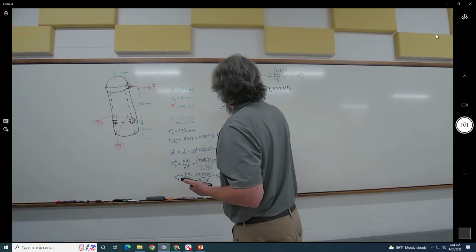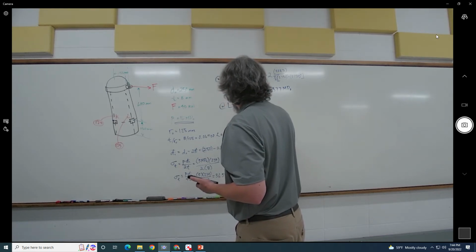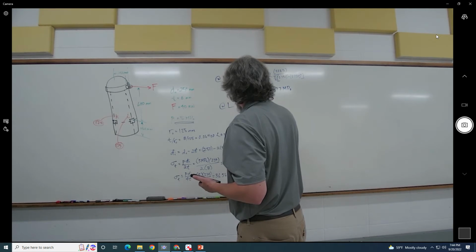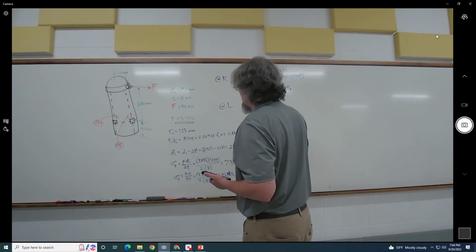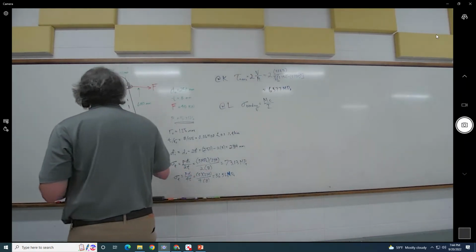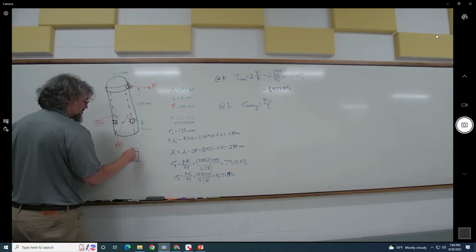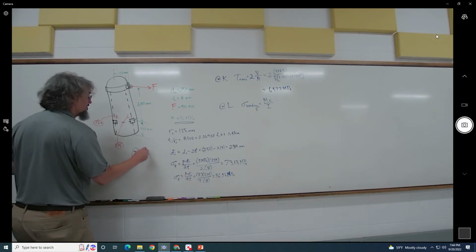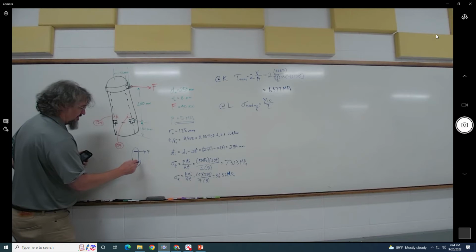And then at L, we could have bending. It's going to be compression, so MC over I. We could kind of do this in our heads, but we could do a little mini FBD, where we have shear coming this way, moment going that way, and it's going clockwise, so this bit would go counterclockwise.